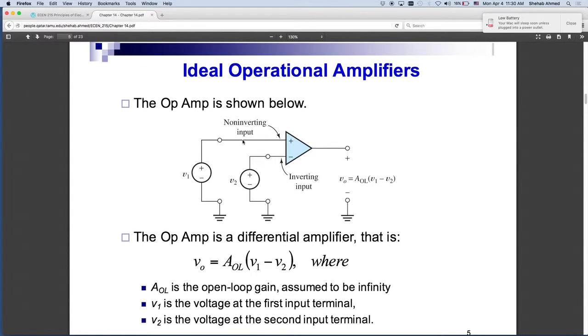Let's say I switch the place of, for the feedback, I use a resistor, but at the input here, instead of having these two parallel branches with resistors, I use one with a capacitor, right? So I'm sort of going to swap: my input signal is now what's being integrated, versus my output being fed back directly, right? That will produce another family of circuits. So this is really what we're going to study in this chapter.